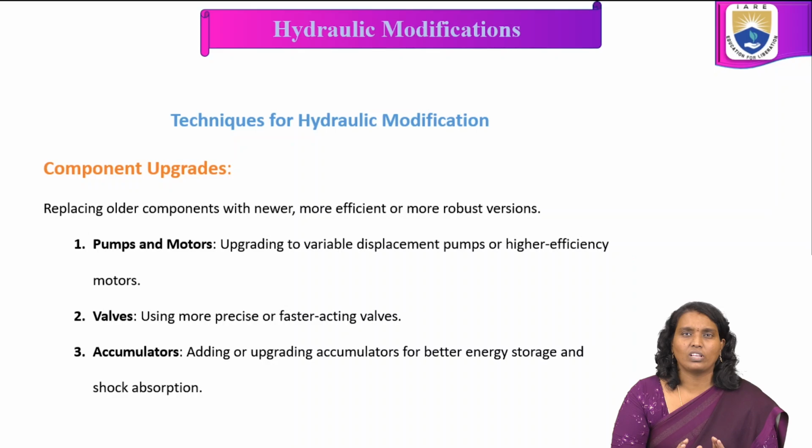Based on the component, we are going to replace the older components with newer, more efficient versions, as different versions are available. In that, the first is pumps and motors: upgrading to variable displacement pumps or higher efficiency motors.